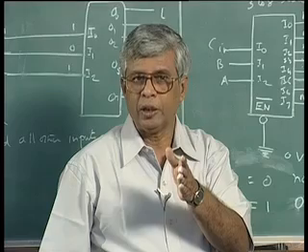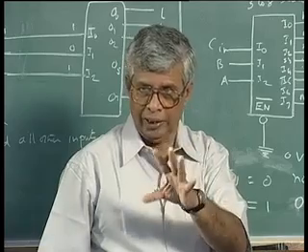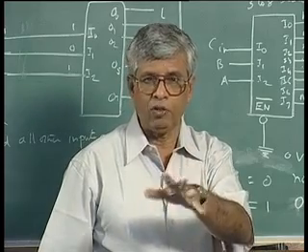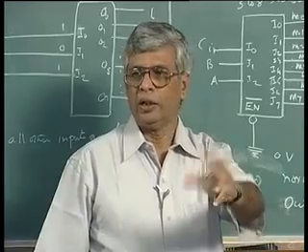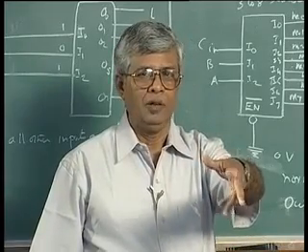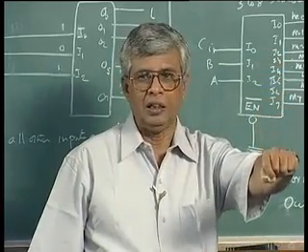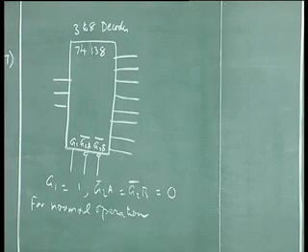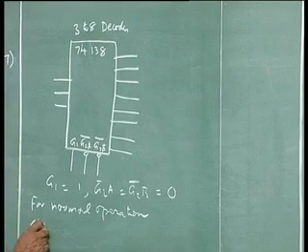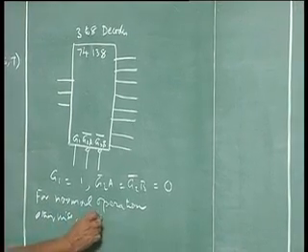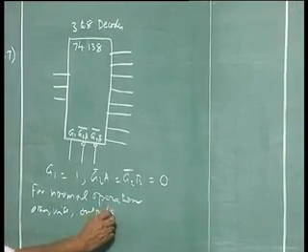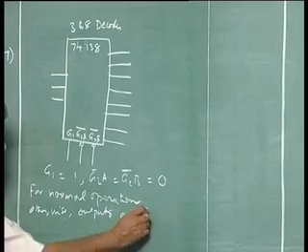As I said, sometimes the control signals, I may have to control from different points of view, from different ways. So, I can use these 3 combinations. Only when all the 3 occur as required, only then the normal operation. Rest of the time, otherwise outputs are tri-stated, otherwise outputs are in high impedance state, outputs are in Z state.